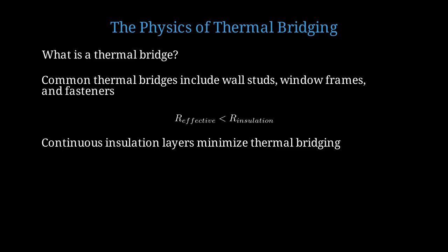Continuous insulation layers that cover structural elements minimize thermal bridging. This is where thin, high-performance materials like aerogel boards excel. They can be applied over studs as a continuous layer.